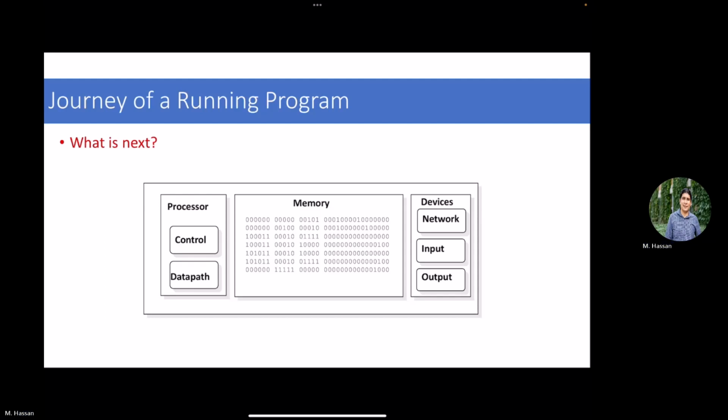Does anyone know? So we say this is a sequence of instructions in the memory. Yeah. Program counter. Thank you so much. And this is something that most probably you have dealt with in the embedded courses, right? Okay, so that's good. Usually, this is also very important for embedded interfacing stuff because you get closer to the instructions. But the idea is that there is a very special register called program counter that keeps the address of the next instruction to be executed.